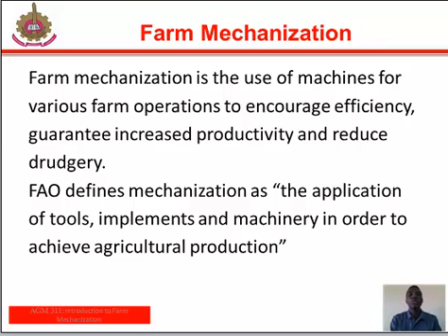It is also the application of engineering principles for operating farm machines with a view to increasing farm operations and output. Mechanization of power-intensive agricultural operations such as land preparation, threshing, grinding, and milling is characterized by non-human sources of energy input to replace human and animal ones required in the operations. On the other hand, mechanized control-intensive operations such as planting, weeding, winnowing, and fruit harvesting require greater human judgment and mental input in addition to energy. Grain harvesting can be thought of as both a power and control-intensive operation.